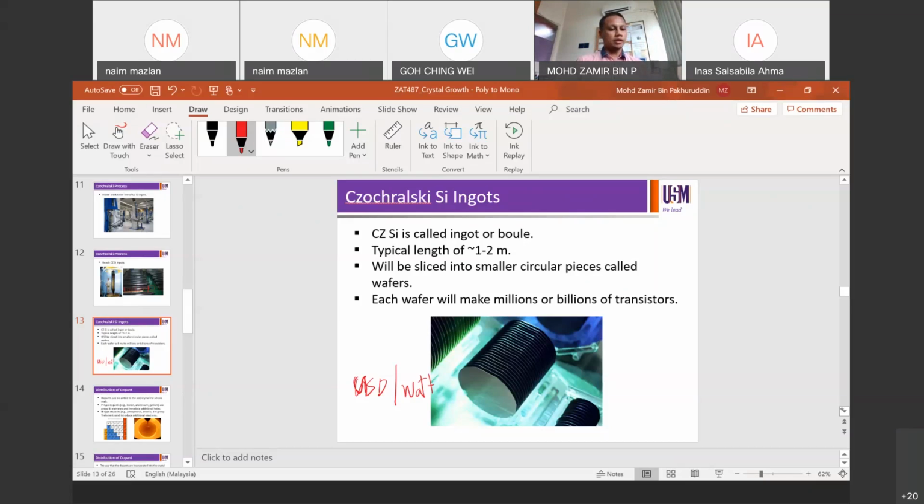Naim, right? MCZ, does it mean impurities are more homogeneous? Oh, okay. What it means is that you can actually minimize impurities coming to the central area of the melt, because the central area will be the main area you want to work on your device, right? So the edge will be the secondary area, if you like.